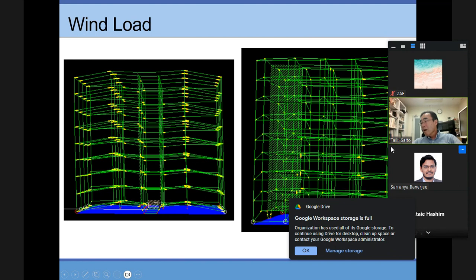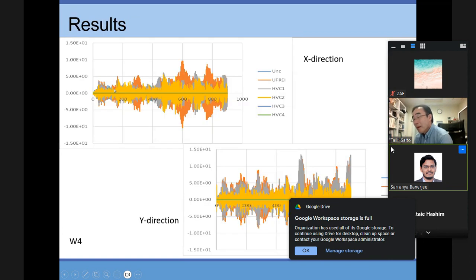But here they are causing some problem. Sometimes I get NaN values due to this error. So I increased the vertical stiffness to the maximum limit for the free sliding isolators, and it is getting solved, but still for one or two cases, and maybe if I divide the time steps further, this numerical error could be solved. But this is one problem which is occurring. Only in one or two cases it is not working, otherwise I have one suggestion.